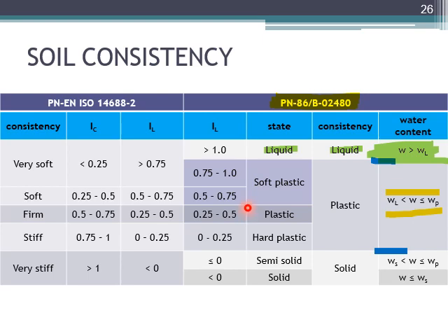If the water content corresponds to the IL value between 0.5 and 1, the soil is in the soft plastic state and plastic consistencies. So everything is nice and clear, right?